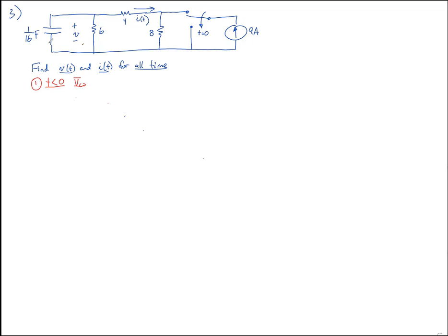The capacitor becomes a, what do you say? An open, definitely an open. And because it's an open, do I even need to draw it? It's got no current going through it. It doesn't affect the circuit. So do I need to draw it? Dontre, what do you think? No, sir. Think about it carefully. You said since it's open, do you need to draw it? That's right.